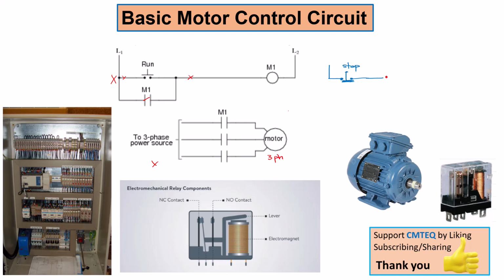Then in line with it, we're going to draw our normally open push button, right? So this is a momentary switch that we are basically hitting to run the motor. So this is going to be the run, okay? So right here in parallel with it is where we've got our normally open contact. That is the seal-in contact, which is affecting our latch circuit functionality. And we're going to have our relay coil here, okay? This is a ladder circuit.